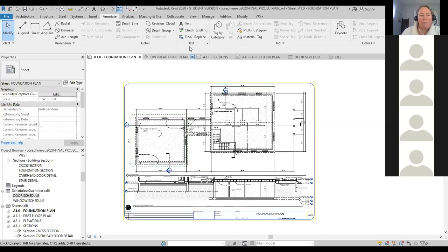There's a really good example of it in the shared drive space that we have. I have two examples. This one here shows what it looks like cutting through a door, and where the insulation goes. And then you've got one on the second floor that shows what it looks like cutting through a window. We only need to worry about the first floor, so I don't care whether you cut through a door or a window, but it would make sense to do that because then it's going to make sense where those headers go.